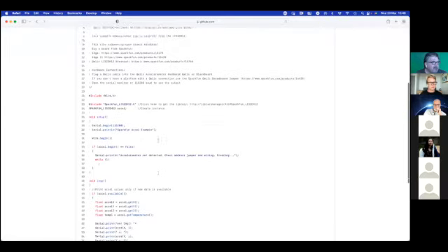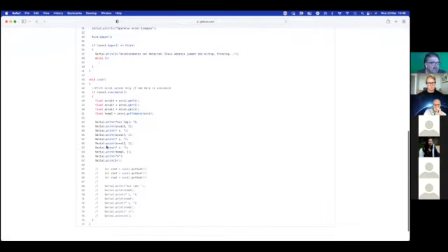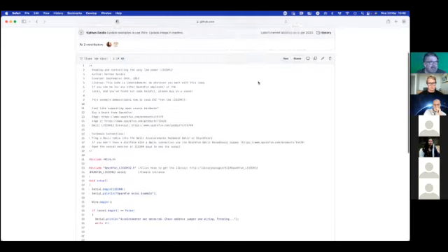It's not long. You can see the bottom here is commented out, so that's not interesting. In reality, other than there's an accelerometer begin up here, which you have to define, begin to see if it can find it or not. You get your acceleration here from X, Y, and Z, and this one can also show the temperature. So here's the code for that. But that just gives the data. Now it's up to you to figure out how you can use that.